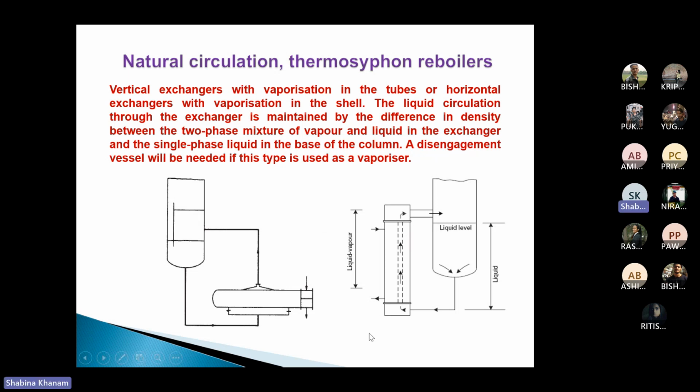So in this way, you can consider the placement and assembly. However, when I consider horizontal placement, it should be well below the distillation column level. Vertical will have sufficient level difference, because it is placed vertically. So in this way, we considered the thermosiphon reboiler.